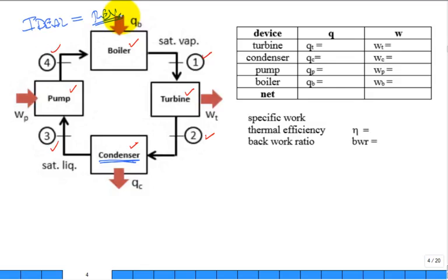But what would logically come out of the condenser? If it's a good condenser, it's going to come out liquid. What came in? Some steam. There was some heat transfer to cool it off, and it condensed. So what logically comes out? Saturated liquid. All right, that's a perfect thing to feed the pump.